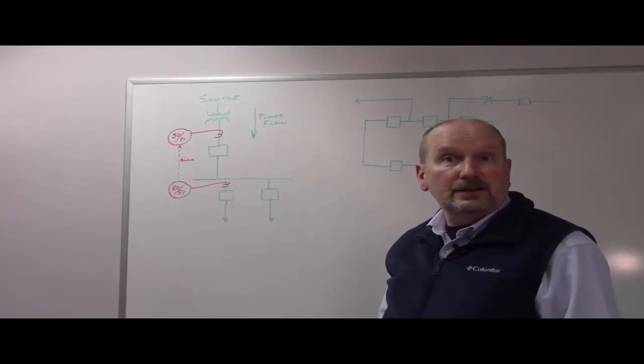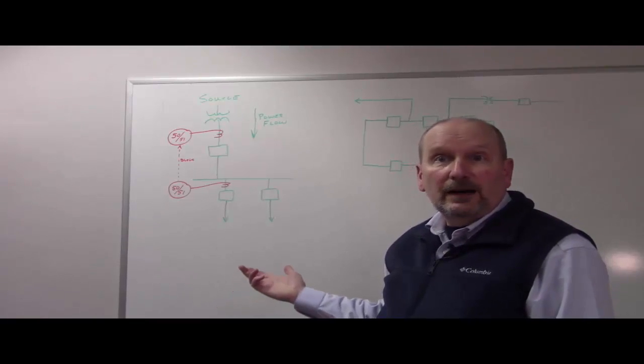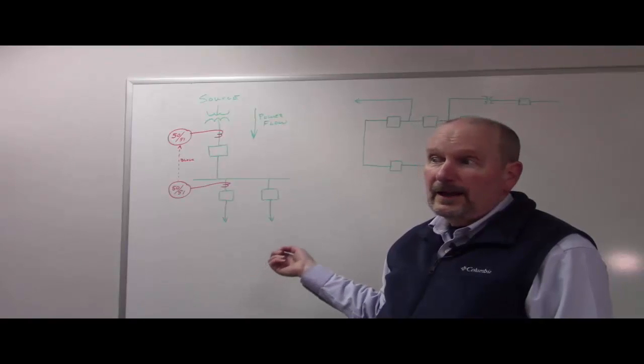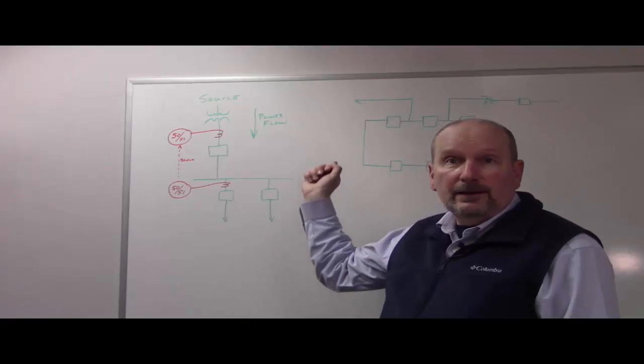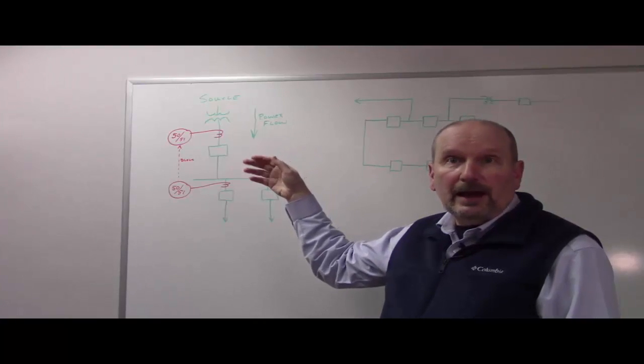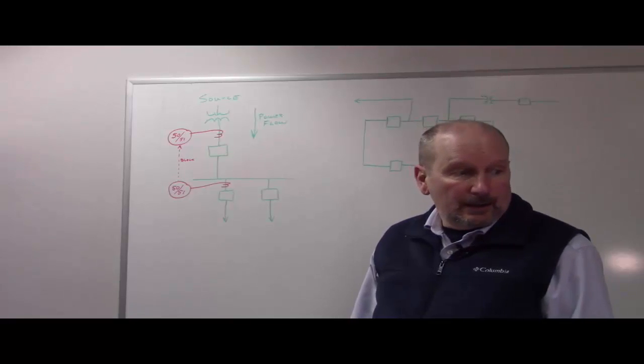This scheme that I just described to you is very similar to the one that would be protecting, say, your house, or a branch circuit in your house. If you have a fault on that and its branch circuit breaker isn't able to clear it, then the next breaker upstream would do that with a presumed bit of a lag behind it.